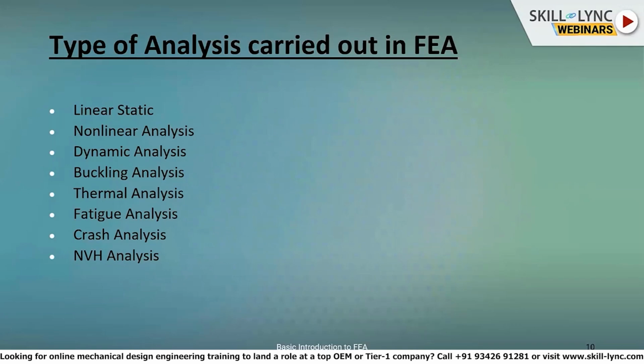Then nonlinear analysis is the analysis in which the load we are applying is incremental in the software. Then we can say that the force versus displacement ratio is not linear in this case. It is nonlinear. The geometry is going under large deformation, so we have to consider the geometrical nonlinearities. The changing shape of the geometry, we have to consider that when we are doing the FEA. Then here we also consider the nonlinear material properties.